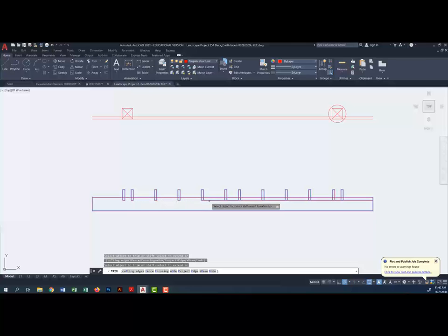Now, typically, I would leave it at this point, even though there's an extra line there. In section, this would be correct, but in elevation, it's not. We actually don't see these lines because, when we're looking at the end of each of these ceiling joist members, we don't see the lintel go through it because it extends or overhangs. So I'm going to remove each one of these just so that we have them properly in place. There we go.